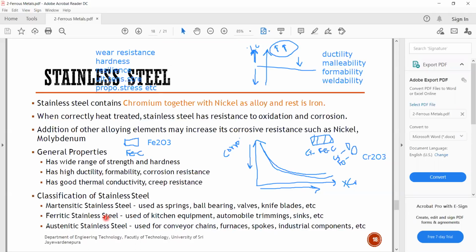Ferritic structure, you are adding nickel, like 5%. Then what will happen? You are forming another steel structure that is called duplex, right? Then again, if you add 8% of nickel, what will happen? You will get austenitic structure, right? So if you need to get the austenitic stainless steel structure, then you need to add nickel, right? So nickel mainly promotes austenitic structure, right?